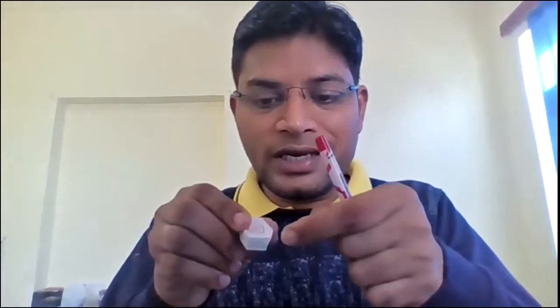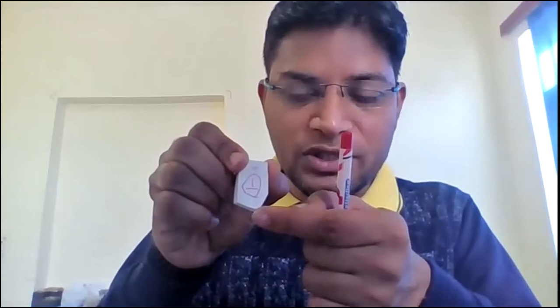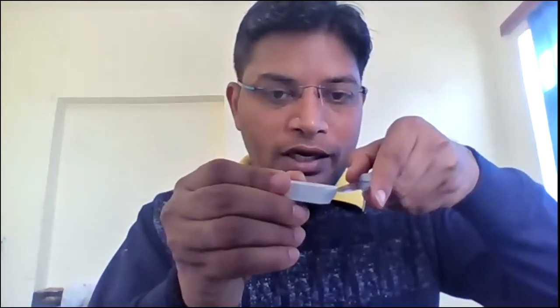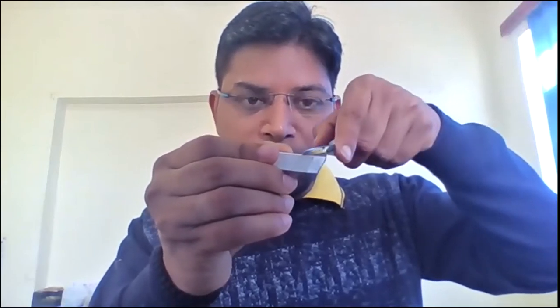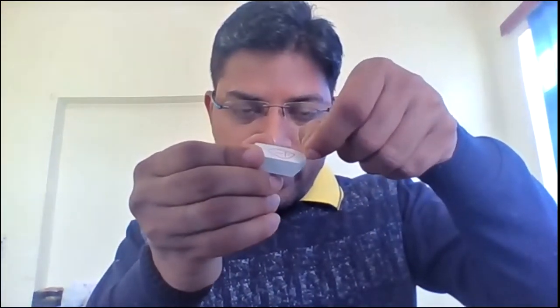So what we have to do is make the chip move in a specific direction. As the chip is coming out from this point, it should move backward. Please listen, it should move backward. So we are keeping the tool, can you see this, this is parallel. Now I am keeping the cutter like that, and I'm removing some amount of the material at some inclination. Because of that, whatever chip is coming out at this point will easily move to the backward side. Please listen, backward side. So that's what I'm doing.